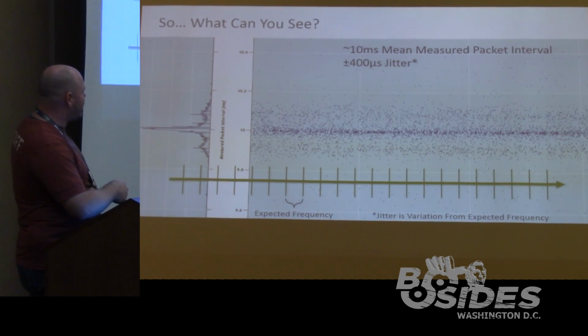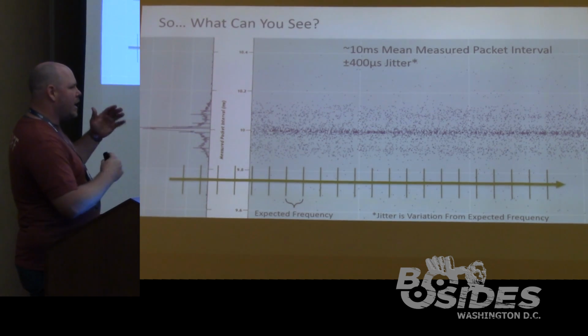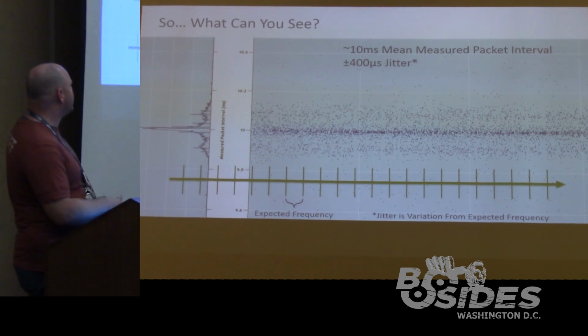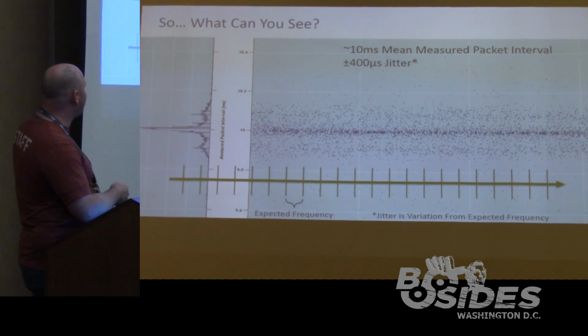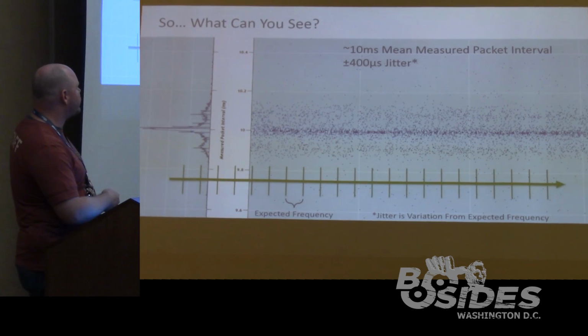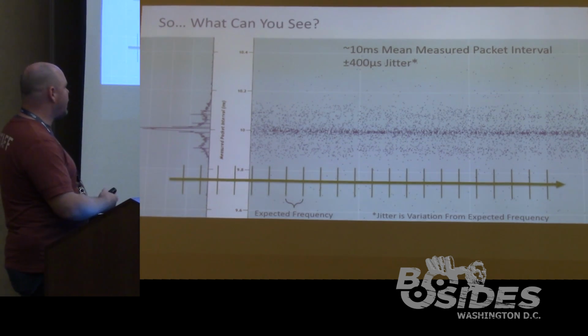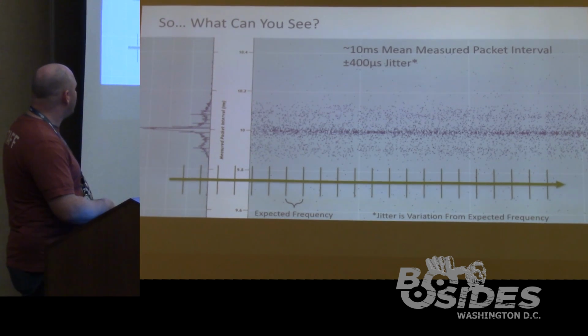These variations are around 10 milliseconds, and as long as you're within a certain percentage, you can consider it a good device. In this particular case, you had 10 milliseconds and a 400 microsecond jitter, so that's a well-performing device. That's something I don't have to worry about.